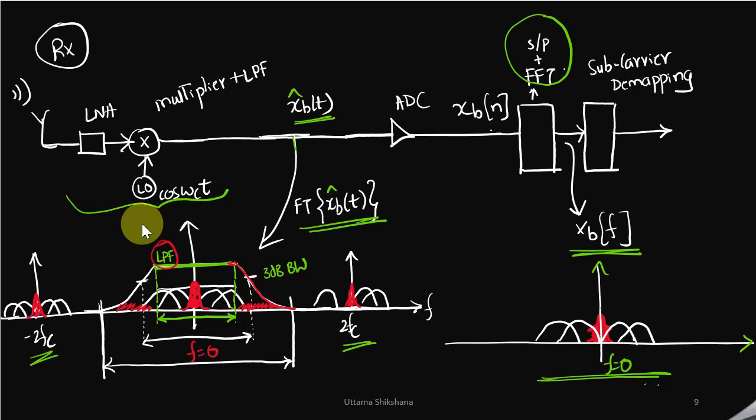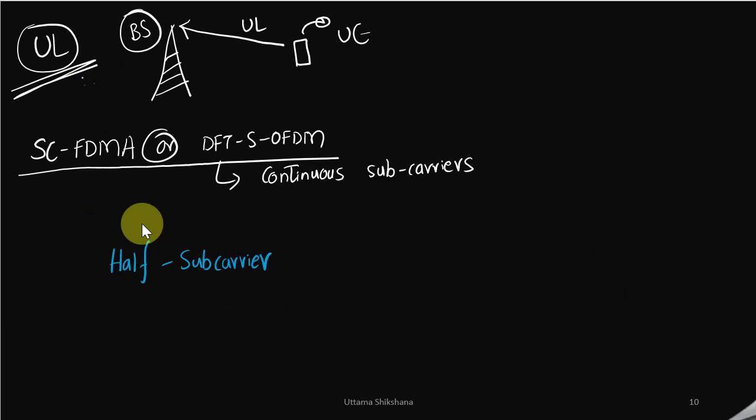After the output of FFT at the receiver part, we saw that there is an unwanted DC present, but there is no information sent on the DC, so there is no problem with this. For further processing, we can just eliminate the DC and take all other subcarriers for the processing. So this concept was very simple, and it did not introduce any extra signal processing block.